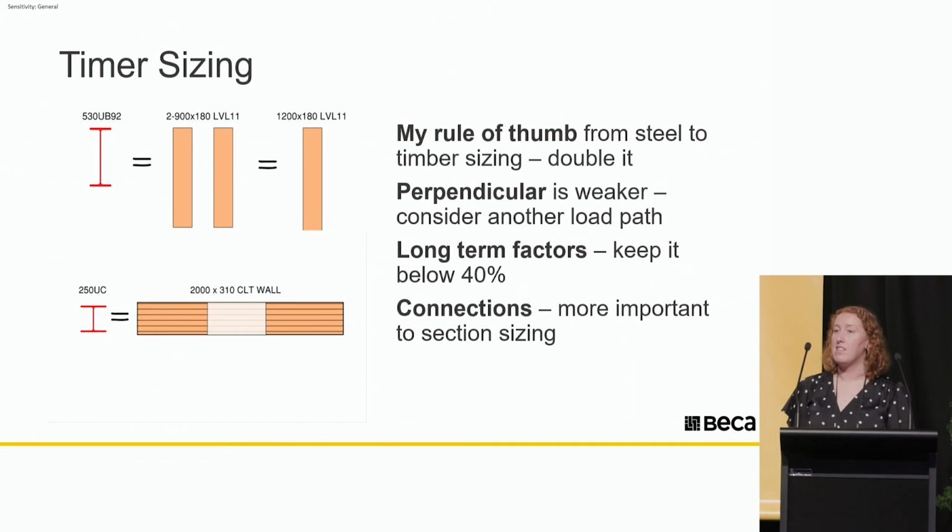capacity. In CLT, you only use the vertical laminars for this compression, so take off another 50%. And then, to make the post-tensioning work, I needed couplers down at the bottom, so I cut out a hole, which took away another 20% of the wall, which leaves about 18% of the original capacity, or equivalent to a 250 UC. So while these two sections have very different structural purposes, this comparison helped me understand and communicate the limitation on the level of post-tensioning we could put through these walls.